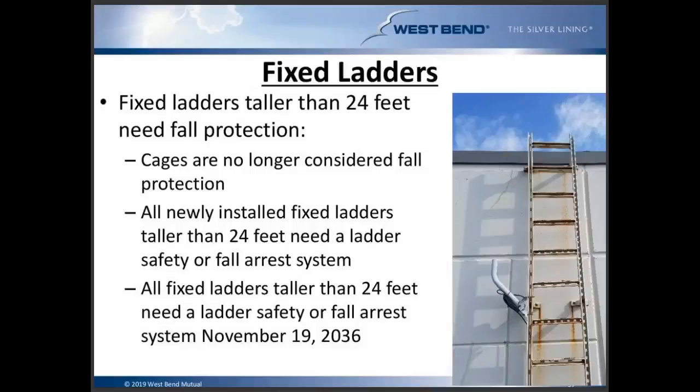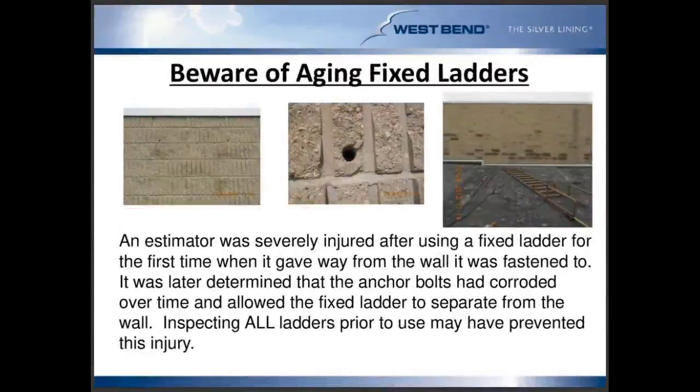The picture that I have included there is just an interesting one. I actually had to climb this one, and there's no 3 feet extended past that upper landing surface, and it made it very difficult to get onto and off of. So again, keep an eye on those fixed ladders. The other thing I want to remind you is to inspect them. Just like all of our other step ladders and extension ladders, our fixed ladders should be inspected as well.